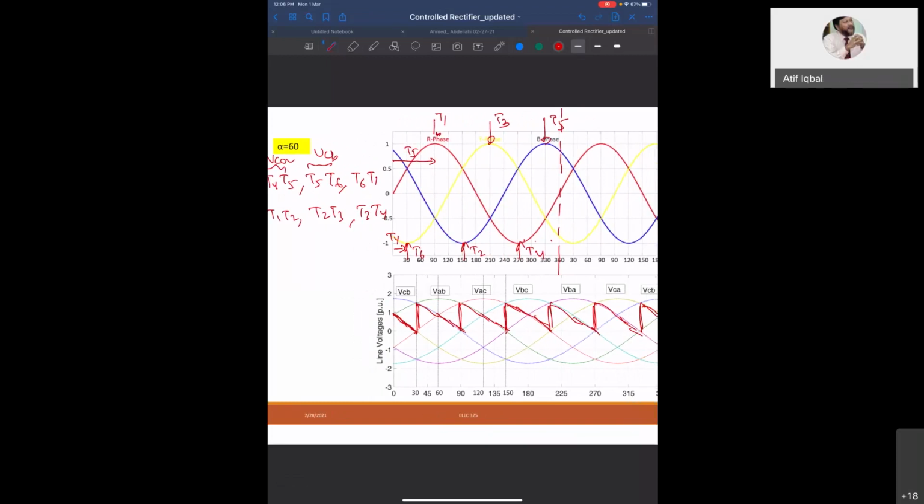Okay. You see here, this T5 should operate for how many blocks? 120 degree. For 4 blocks, each of them for 120 degree. Overall, you will see that it will be having like 60 degree pair. Now, this is one block. Because at this point, you have now finished your cycle. So next 3 will be here. For T5, one block here and 3 blocks here. Got it? For 5, okay. And now for 4, check.